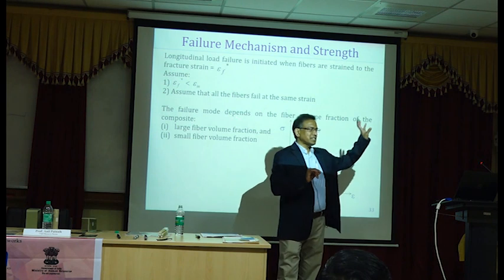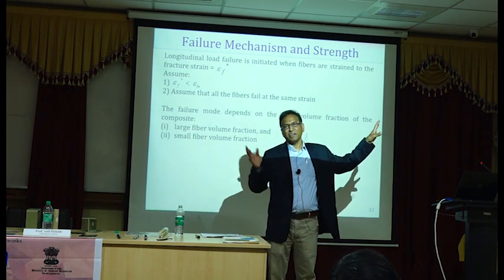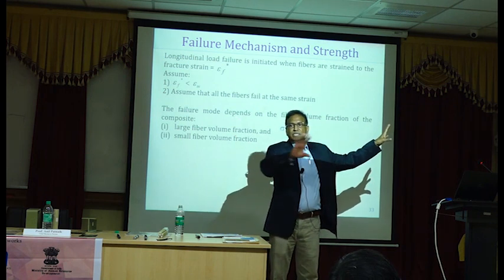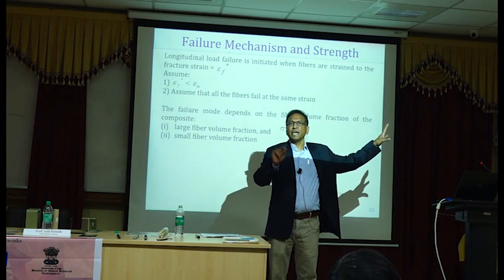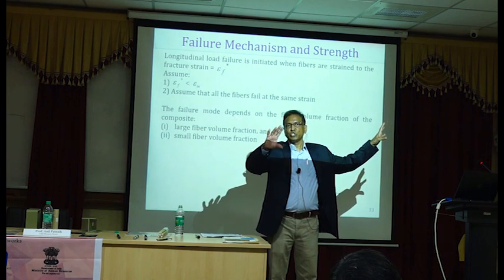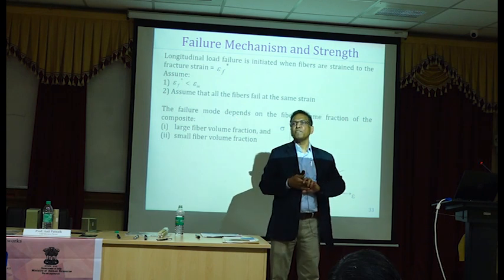So let's say that's 10 kilonewtons. I'm just throwing out a number. It may not be 10, it may be something else. Now you design a beam considering a cracked section with reinforcement. That strength should correspond to a load of 10 kilonewtons. That's the basis for minimum reinforcement.